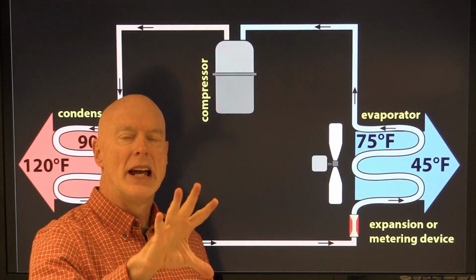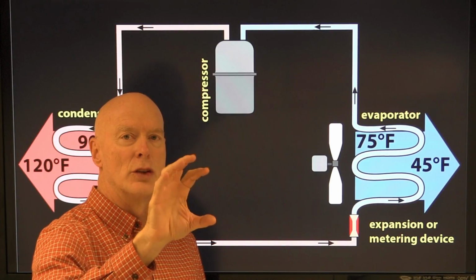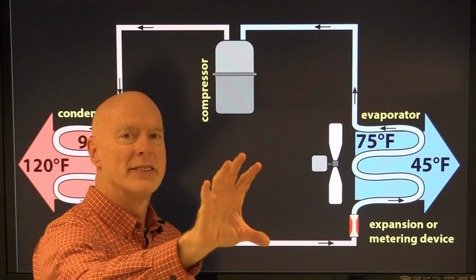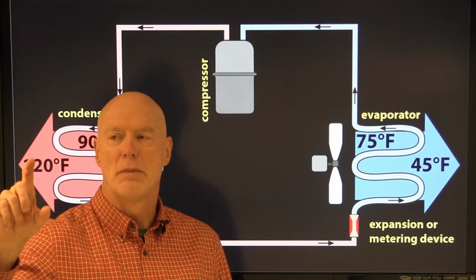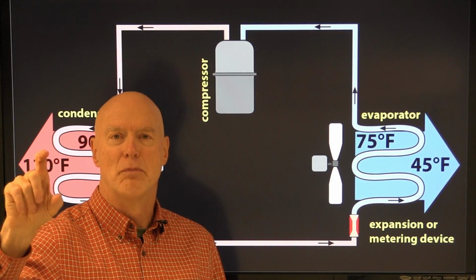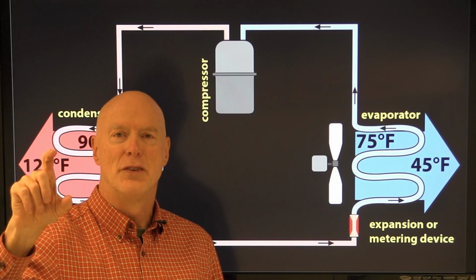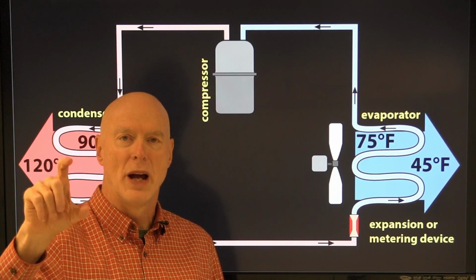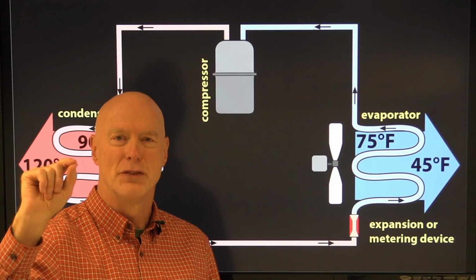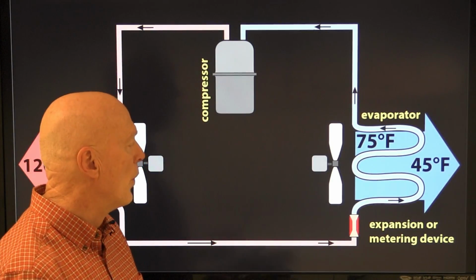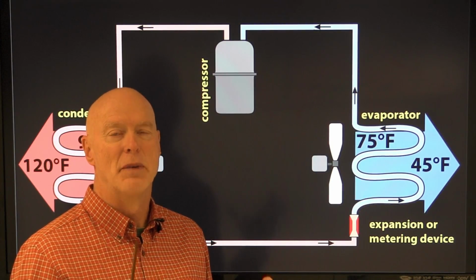And as it gets sprayed, it's turned from a liquid into droplets and then into a gas. And when that happens, it's like when you take hairspray or spray paint and you push down on the button of that spray, and what do you feel in your finger? Well, your finger starts to feel cold, and if you sprayed for long enough, even if it was a warm day, you could frostbite the end of your finger. And that's because when a liquid is turning into a gas, it is sucking heat from everything around it.